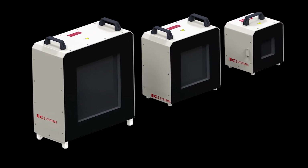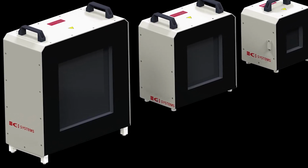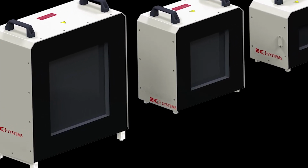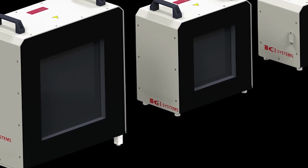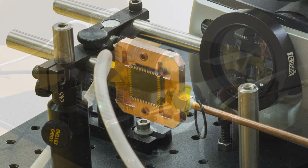The very important parameter of the chip is what is called an apparent temperature. This is the temperature of a black body which would emit exactly the same type of radiation. Our testing showed that the chip which we can produce can achieve apparent temperatures in excess of 700 Kelvin, actually approaching 800 Kelvin, both in the mid-infrared and the far infrared. We expect that with the optimization of the chip design, we'll be able to reach 1000 Kelvin as apparent temperature in both bands.